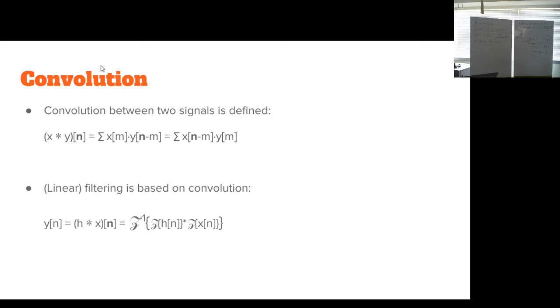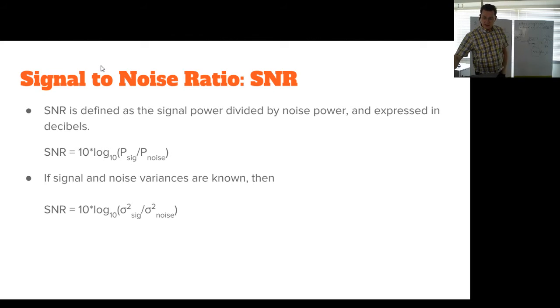Well, if you take a look at the Fourier space, meaning if you want to have a signal filtered spectrally, you actually want to multiply the signal spectrum with a desired filter spectrum. That's actually what this mathematical mumbo jumbo here means. But anyways, that translates back to linear convolution in time space, meaning that now we have a method to calculate the filter output in time space. You do not have to go into frequency space doing these ugly calculations. You do everything in time space using convolution. Not too many slides, don't worry.